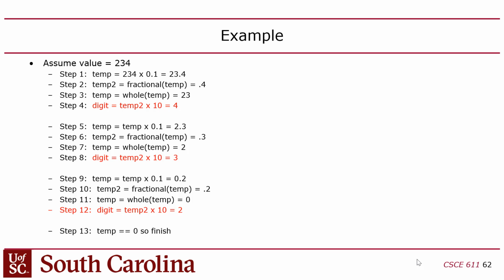So what I'm saying is that you have to do 3 total multiply instructions. You need 2 multiply instructions in order to multiply your value by 0.1. Why do you need 2? Because one gets the upper bits of the product, which is the divide, the quotient, and the other one is going to help you recover the modulo, which is the fractional part, right?